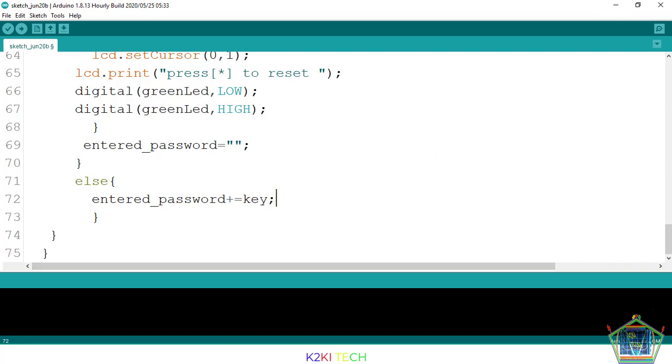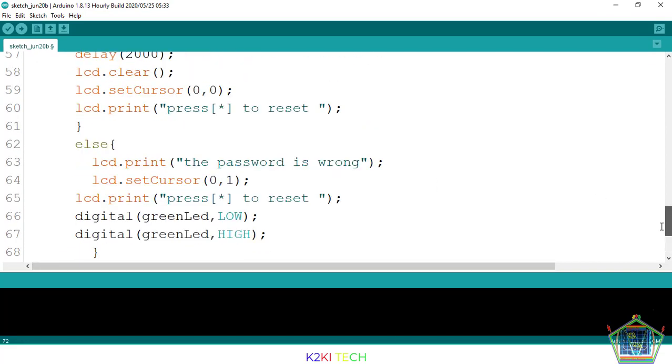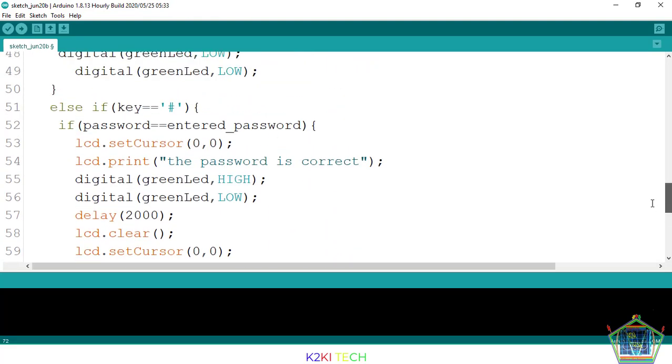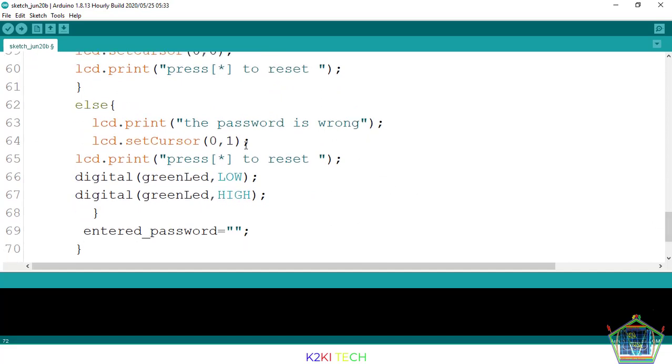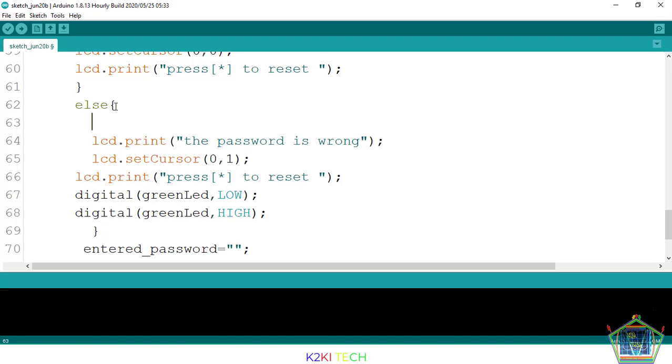Then after finishing up with this program, let us try to hit run and see whether what we did is running well. But before that, see, there will be a confusion in the LCD because we didn't clear the first printed message. LCD.clear, and then close with a semicolon.